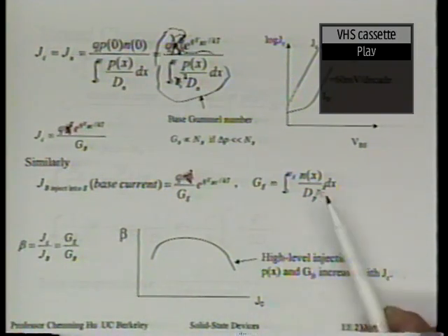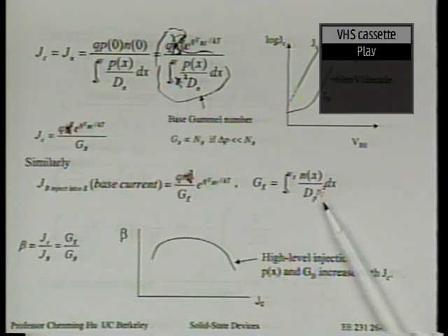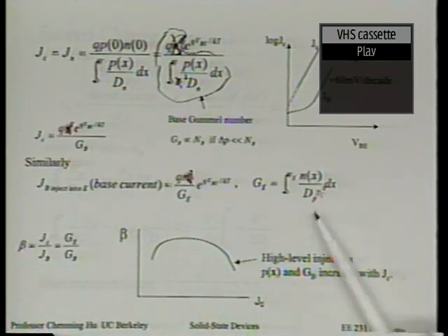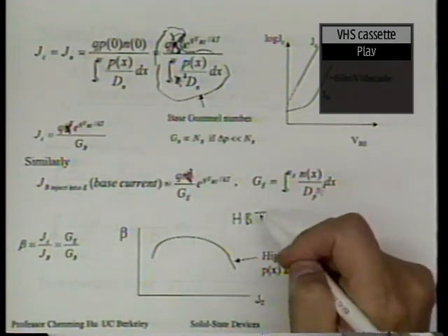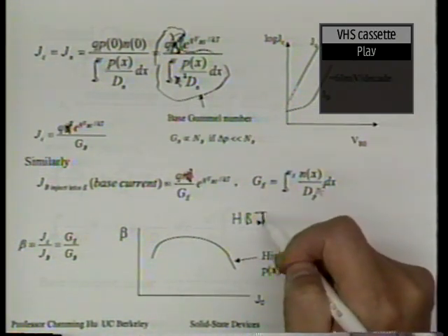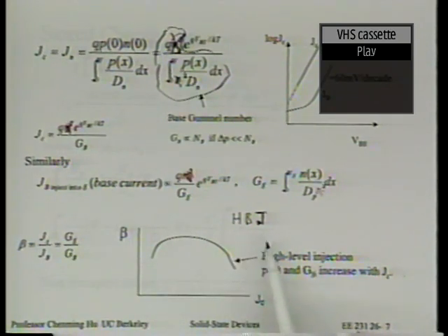Now, for example, if you are using a gallium arsenide transistor today for RF applications, for an RF power amplifier, what you will find is the base is made of gallium arsenide, and the emitter is made of a material with an even larger band gap than gallium arsenide, such as gallium phosphide or gallium aluminum arsenide. Anytime the base and emitter materials are different, we use the name heterojunction bipolar transistor, or HBT. I don't think people call it HJBT, just HBT. That means the emitter-base junction is made of two different materials. Heterojunction.